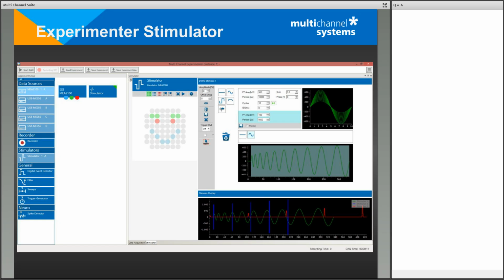So here, for operating the stimulator, you have a display of your electrode field. You have 3 different stimulation lines. You click the stimulation line that you want to use, and then simply click on the electrodes that you want to assign to that stimulation channel. You can start and stop independently one channel or all of them. And over here you define your stimulation pulse. You simply take one of these so-called primitives, so these standard waveforms, and drag them down here to generate the complete pulse. Can be as many modules or primitives as you like.